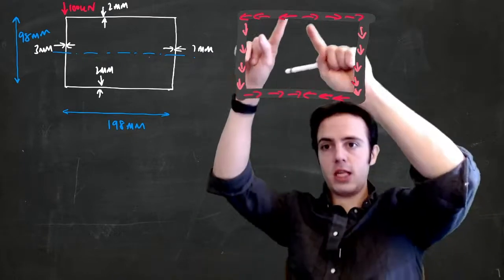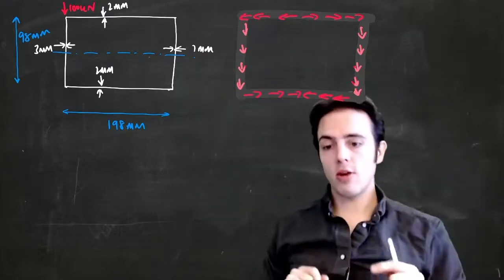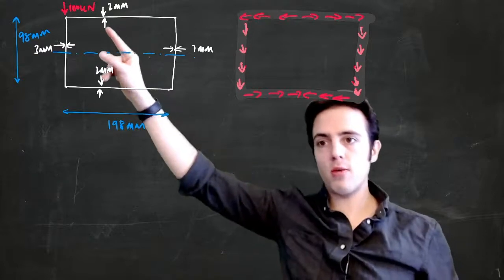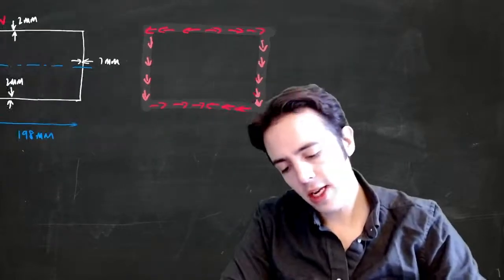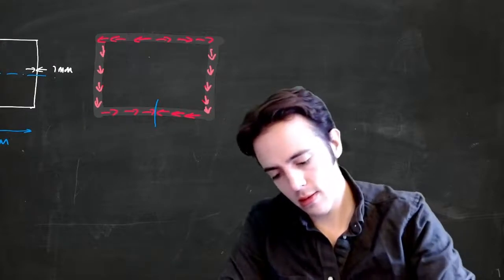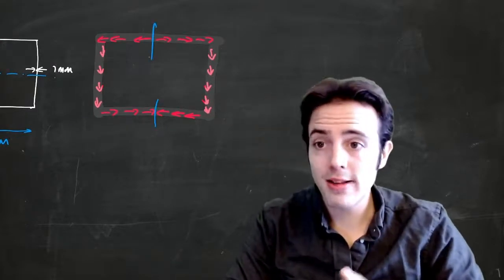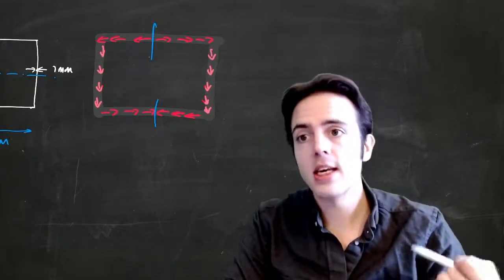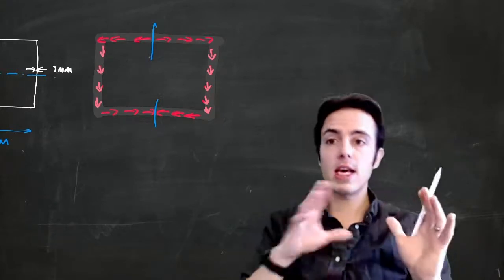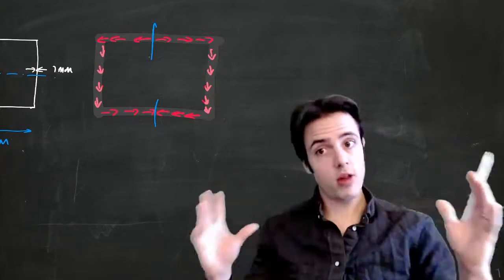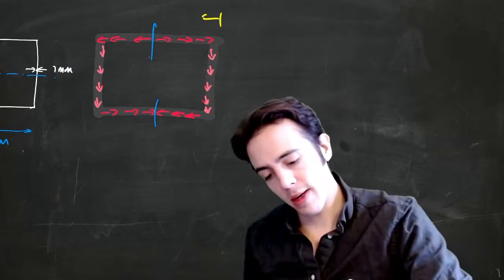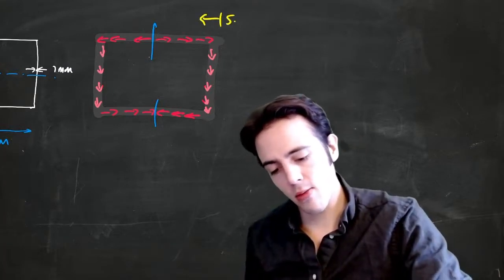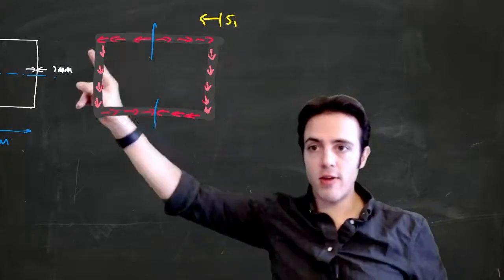So we've got a continuous distribution in this object due to applied shear force, 100 kilonewtons, and we're going to determine what these actually are. The significance of where the arrows change direction is that there is a sign change in the definition of the actual size of those shear flows that we determine. So, for example, we're going to say this is S1 defined in this direction.